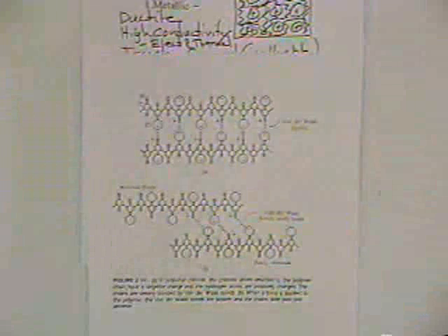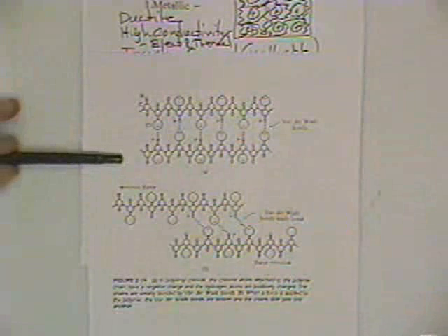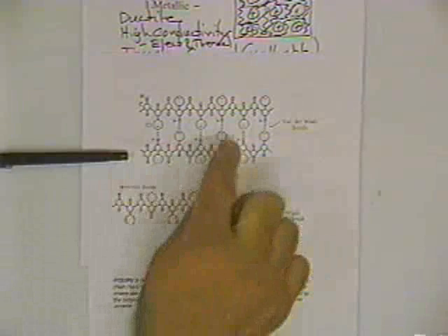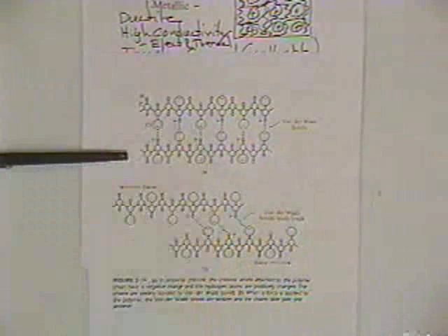This picture corresponds to PVC, polyvinyl chloride. Much of our outdoor drainage pipe is made from PVC material. And if we look at the chain here, within the chain, those are covalently bonded. Carbon-hydrogen bonds, covalent, very strong, and the chlorine atom that's in there. However, between the chains, as designated by these plus and minus regions, these little polar regions, there is a weak attraction.